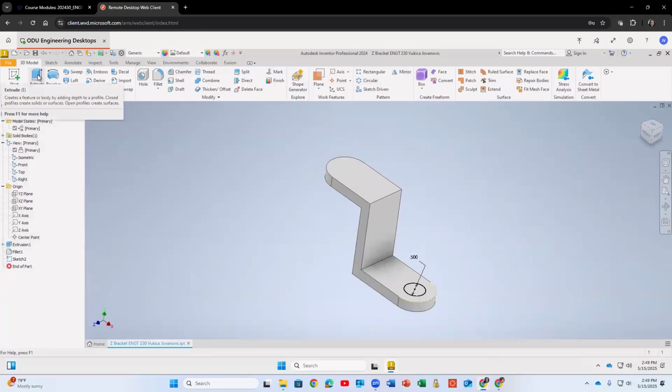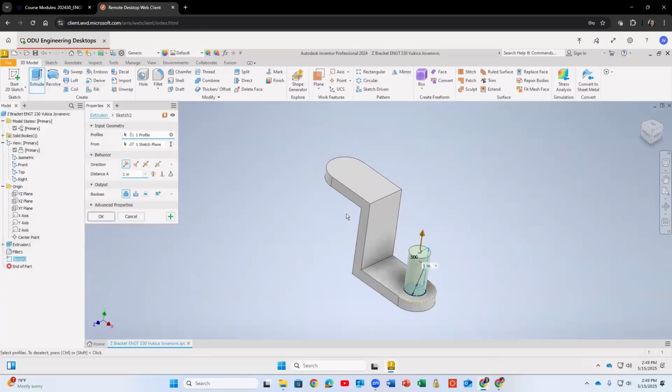And again, in this software, I'm saying extrude. And you see, you can add material, or you can switch here. You see Boolean output. You can go here to cut, right here, cut. And how do you know when you're finished? You see there are different distances, but I can switch to through all. So you see, I don't care how big it is. If I change something else, the hole will still go through. So I like to use, you see, this cut distance A2. So just make sure you see these different ones.